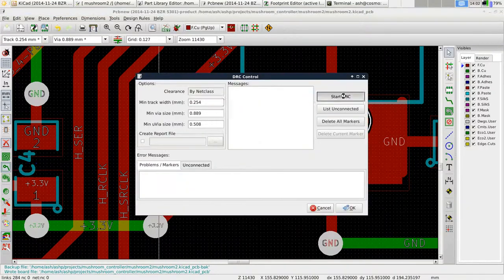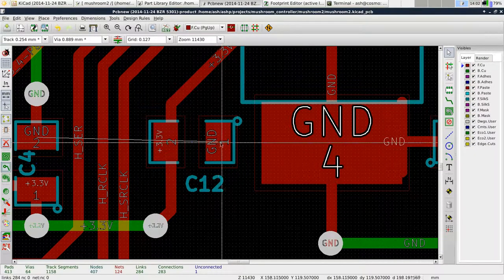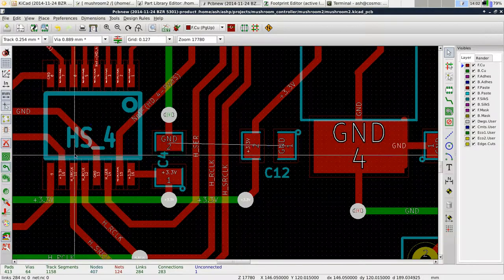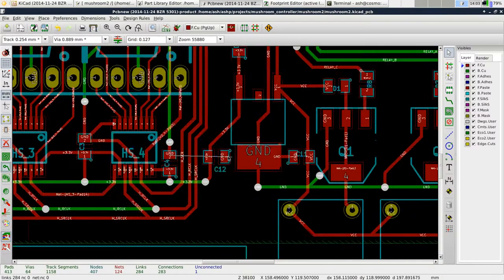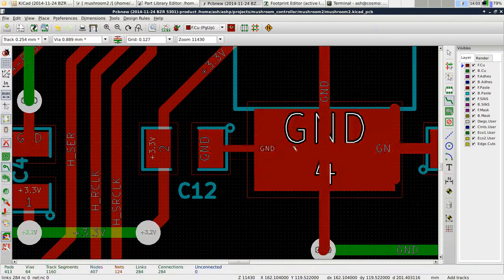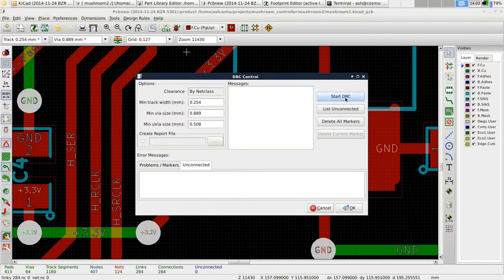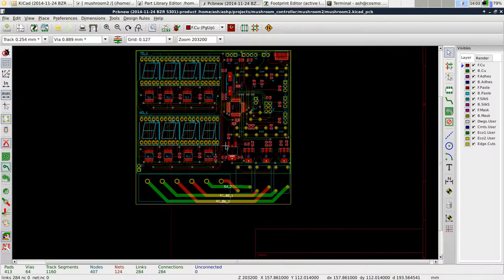And what you'll see is, if they're not connected, it knows that that has to be connected. Because if I do a design rules check and list unconnected, it will say, look, that is not connected to ground. And you'll have what's called the rat's nest, which is all these wires like this, that white thing, which when you first do this, it will just be covered in that rat's nest. And what of course you want to do is connect up all of your things until you can run the design rules check, and you get no unconnected things. So everything is connected. So when you first import the netlist, you just have a bunch of footprints on there and tons of rat's nest everywhere, and then you need to lay these out and connect them up.